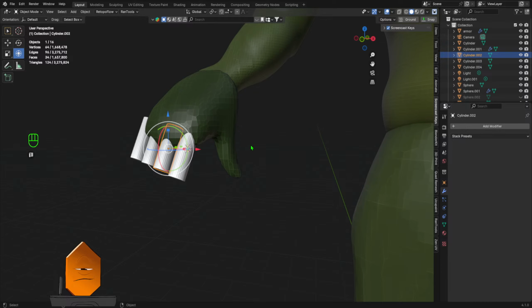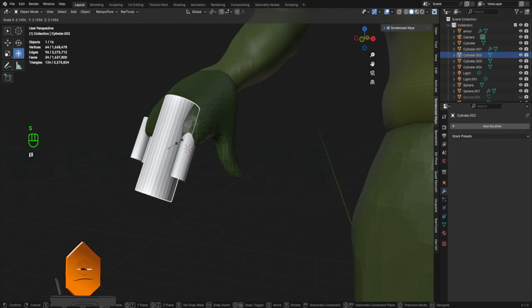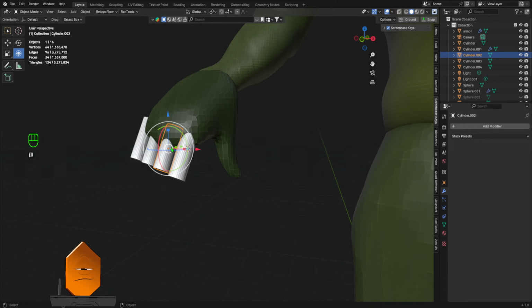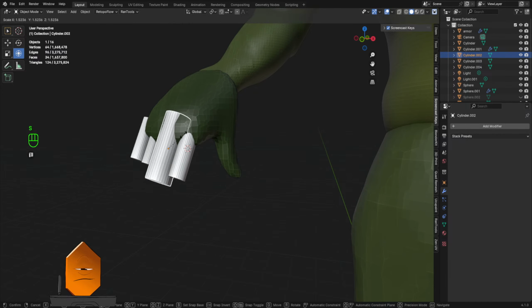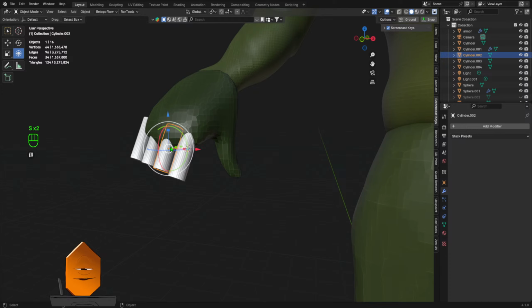Also, just in case you don't know, I imagine almost everybody here does, but when you're trying to make changes in Blender, the closer you are to the axis of transformation, the origin, basically, when you make the transformation, the larger an effect it's going to have. So if I want to scale this very precisely, I don't want my mouse to be anywhere near the origin. I want it to be over here.